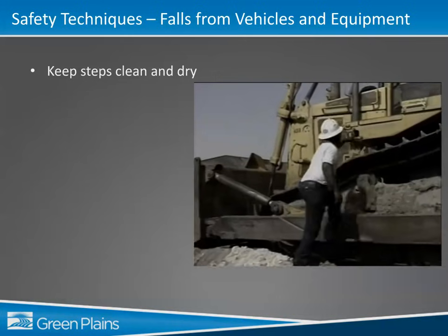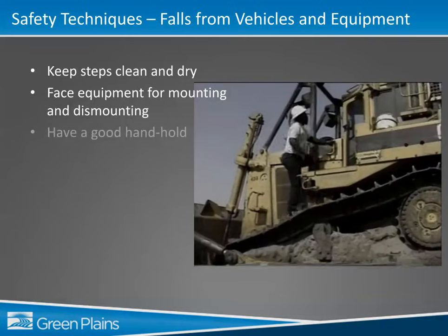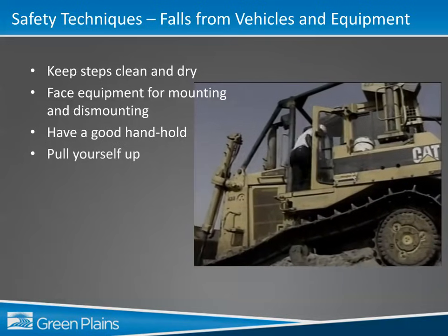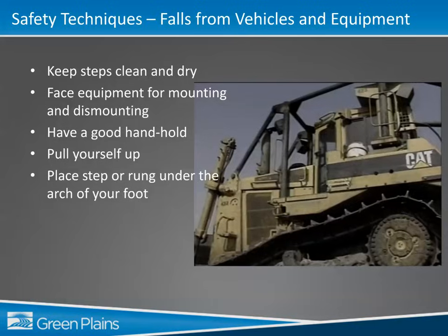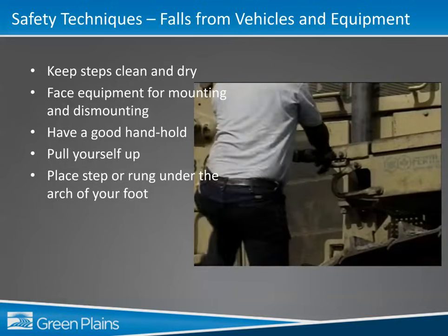Whenever mounting or climbing on a vehicle or machine, always face the vehicle or equipment and have a good handhold before stepping up. Pulling yourself up reduces the force between your shoe and the step, which reduces the danger of a slip. As with a ladder, the foot should be placed on the step or rung just in front of your heel under the arch.